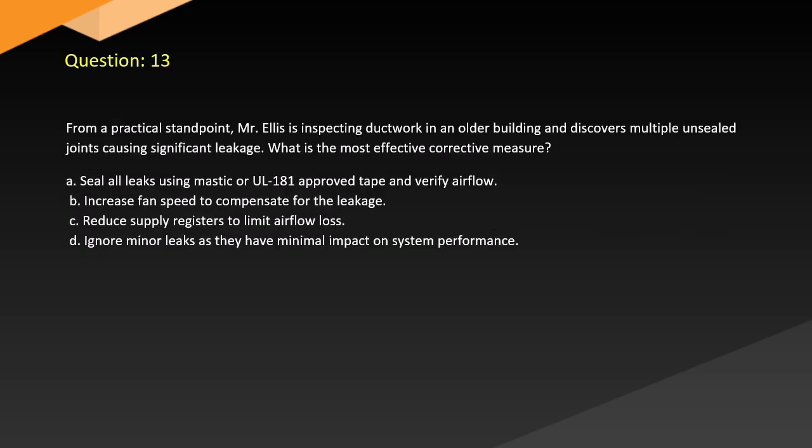Question 13. From a practical standpoint, Mr. Ellis is inspecting ductwork in an older building and discovers multiple unsealed joints causing significant leakage. What is the most effective corrective measure? A. Seal all leaks using mastic or UL 181 approved tape and verify airflow.